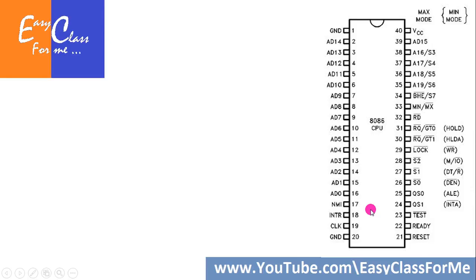So on what factor does that depend? That depends upon this S5 bit. The address pin 18 is time division multiplexed with this S5 pin, and this S5 pin indicates the status of another flag called the interrupt flag, which we have not seen in the previous architecture because it is not usually shown in that diagram. The interrupt flag indicates whether the processor is ready to take your interrupt request or not, and it is given by this pin number 36 in time division multiplex fashion.